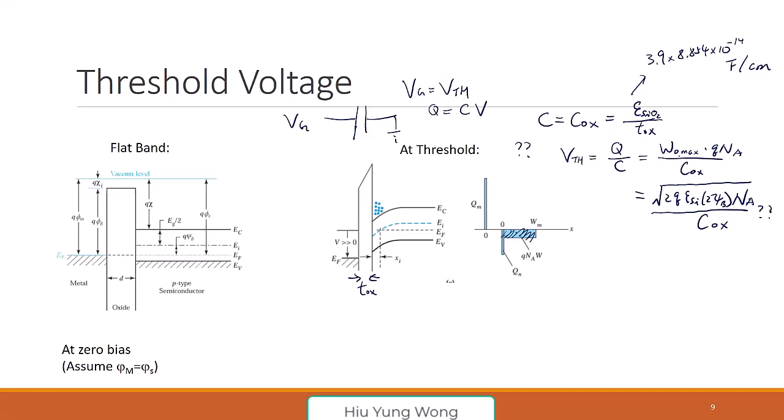So you see that maybe none of us have thought about this before because we didn't have time. The threshold voltage is just equal to the voltage at which I have this amount of full depletion charge on the other side, just divided by Cox. Is this correct?